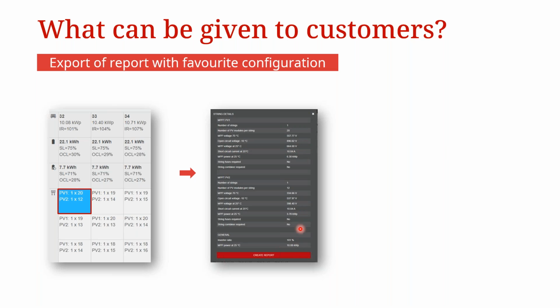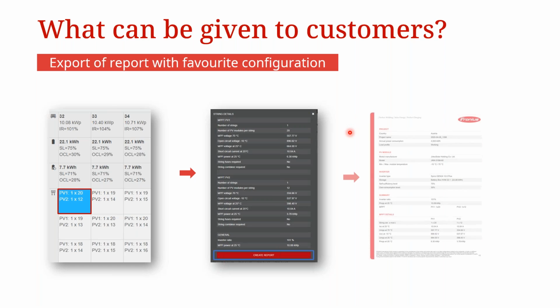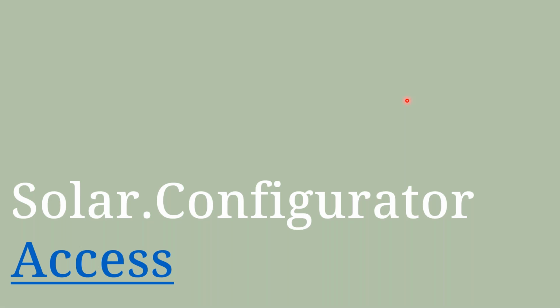So this data is very well generated, and when you are going to connect your string, you can use a multimeter to confirm the string voltage as calculated using the solar configurator. In addition to that, you can also generate a proper PDF report for the entire design. Unfortunately, it's not very well visible here, but outside of the string, the solar configurator can generate this kind of report that is going to show you the exact design that you're working with, and give it maybe to your installation team, so that when they go to the field, they're not going to make any mistakes.